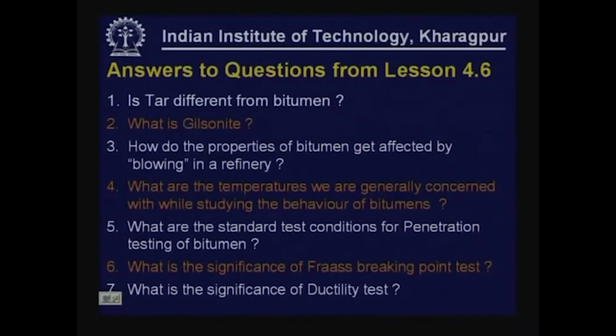What is the significance of ductility test? This test gives us an indication as to how much the bitumen can be stretched at a fixed temperature, how far the bitumen films can be elongated at a given temperature.